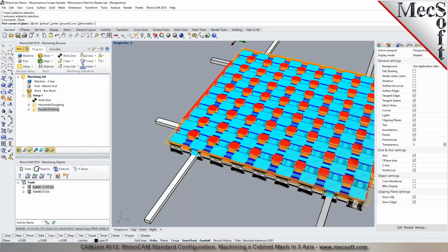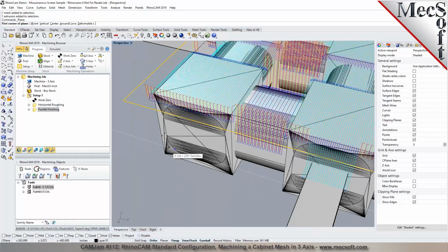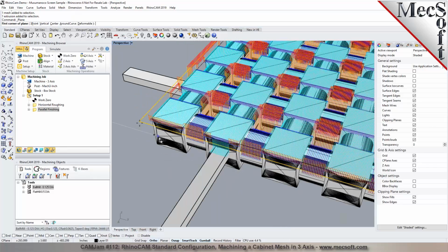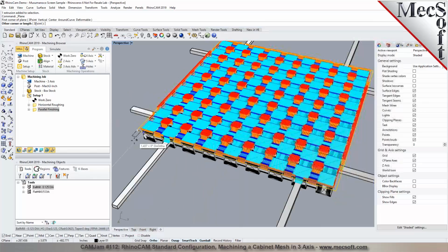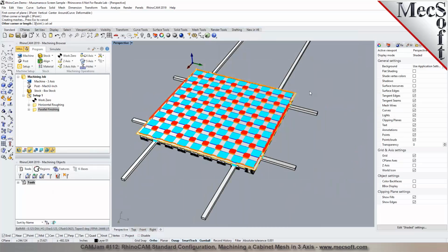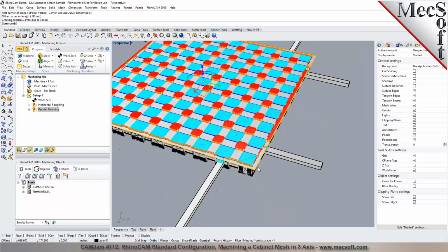For instance, if you put a surface plane, let's see if it'll grab the midpoint of that. It's not going to find a midpoint. So let's create a surface from, since there's nothing to pick from, it's a mesh. I wanted to pick a midpoint, but you can't pick a midpoint on a mesh since it's mesh geometry, not curved geometry. So we're just going to pick this, and then put it over to here. You see there's a surface there on the top.